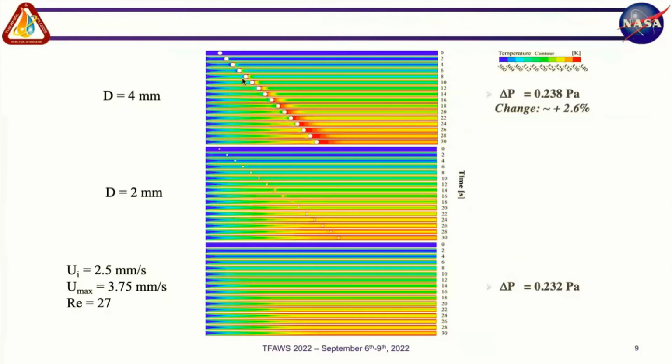We just see the enhancement here of the pumping effect, let's say, or the piston effect of the particle pushing the hot fluid down. You can clearly see how hot the fluid gets ahead of the particle. The rod, remember, is temperature 340, so you're almost in thermal equilibrium with the walls of the particle. So this region here will be a very bad heat transfer region, we assume, because you no longer can transfer heat from the wall to the fluid, because the fluid is now in thermal equilibrium with the wall. But of course, downstream or upstream of the particle, you have that pushing effect or sucking effect of cold fluid, and we need to check what will be the difference between the two.